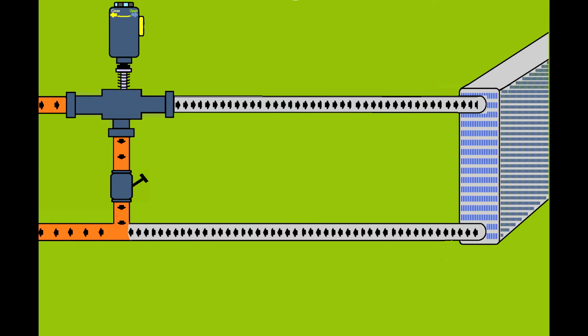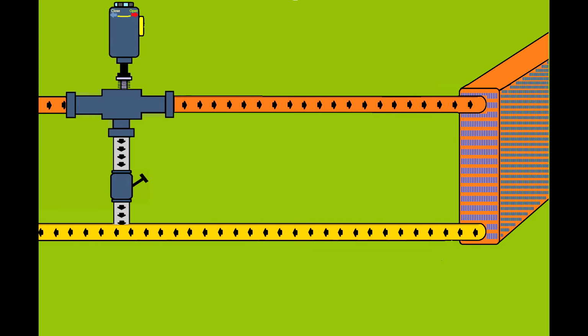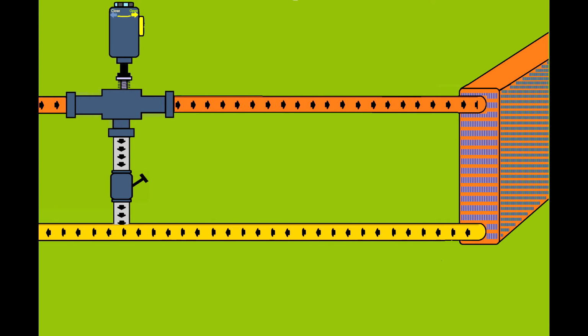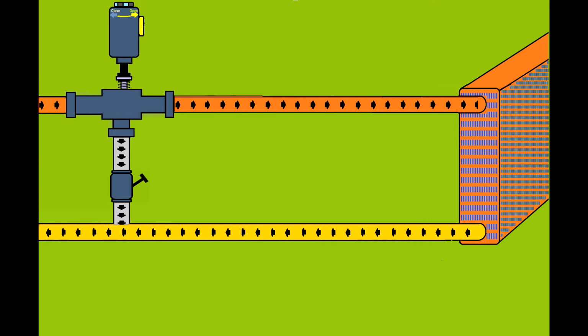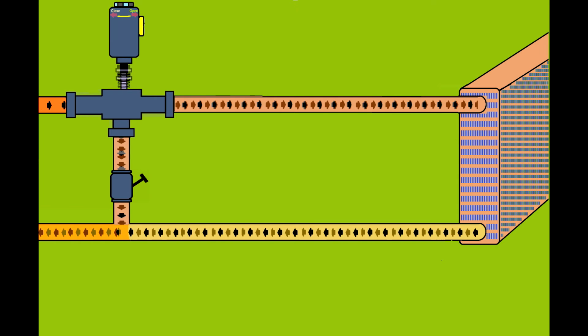Now you divert the heating agent because you don't need flow, and what happened just now is you will have heating agent passing by to the heat exchanger, and part of it is diverted, because this valve is not 0 and 1, it is from 0 to 100%. So now the capacity is 100%. You will have all the heating agent passing by to the heat exchanger, and what you'll see now is diverted again.